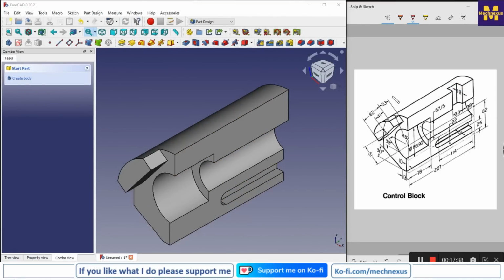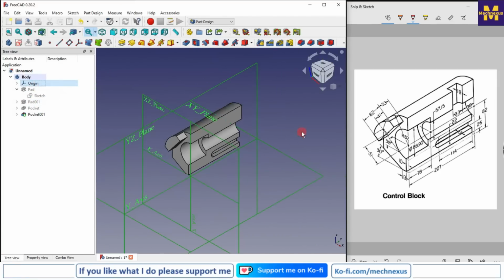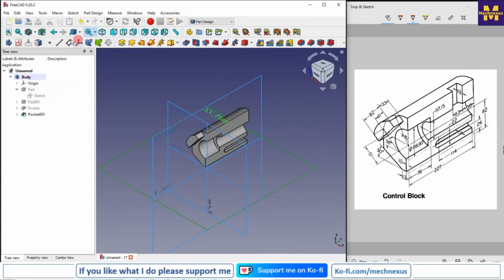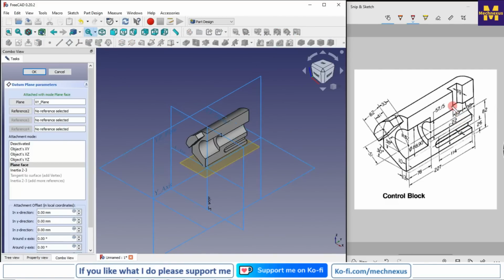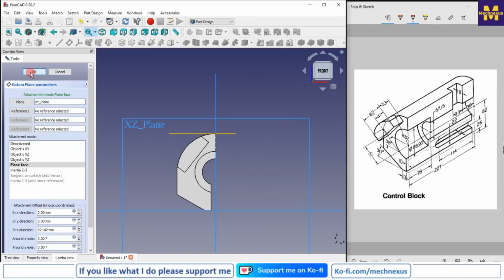Now we will make this rectangular cut at the top. So for this we require the datum plane. I will select my XY plane on my origin plane and click on the datum plane, and here the outermost radius is R82, so I will give my dimension 82 here and make it negative, so flip the direction. Okay, so 82 plus 82, because radius is 82, so we want diameter, so 82 plus 82, so we have the datum plane.